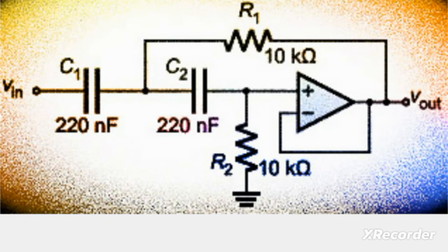So that's the advantage of using it as a buffer or voltage follower, and the output voltage is equal to the voltage applied or available at the positive pin of the op-amp. That's why it's called voltage follower. So we don't really have a gain because output divided by the input is equal to 1. That's why we call it a voltage follower. Output voltage follows the voltage at the input.